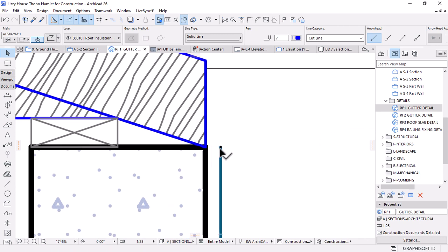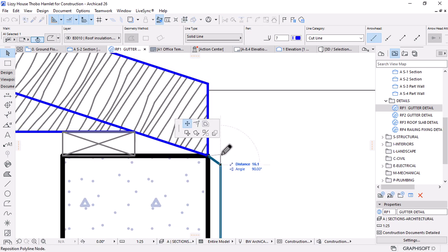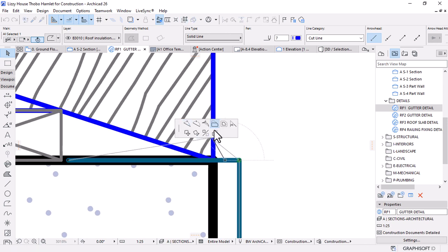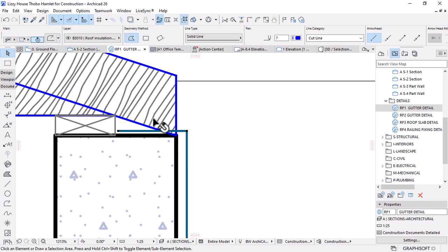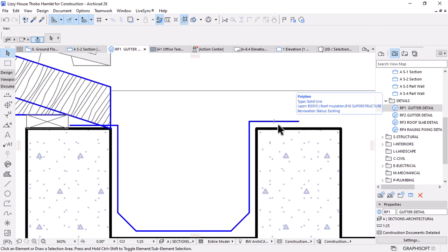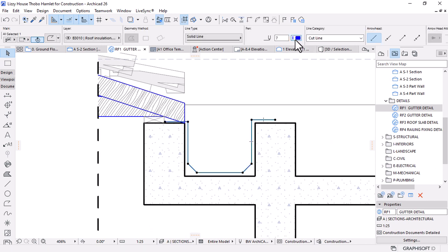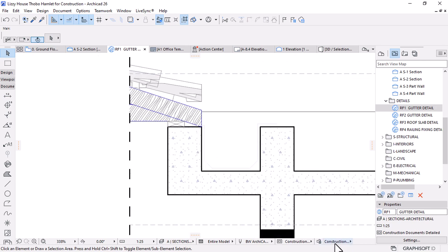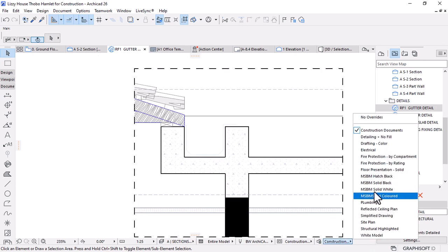And this metal sheet is going to go underneath it to restrict water from getting inside, I mean, to penetrate our slab, our concrete. So it's going to be under your truss like that. So let's just do this. And then let's set this to 0.5. It's not visible, but we'll see. I can just use a different color, maybe solid black.